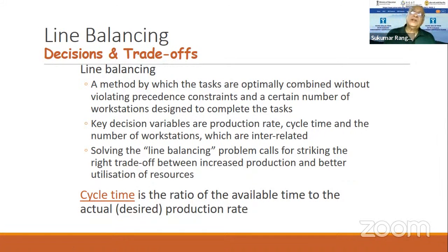The entire process itself will have a cycle time determined by the bottleneck process. So if you remove the bottleneck everywhere, then you will have a very clean, most efficient throughput for that particular line.